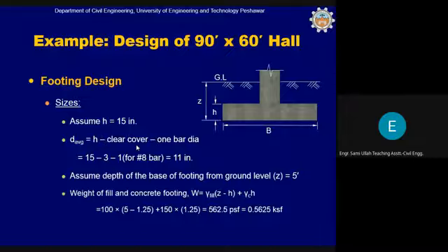So the contact point of these two means that one complete bar diameter will be added with this 3, plus 1 inch. Total is 1 inch, which is the diameter of one bar. This will be deducted from this for D average. This will come out to be 11 inch.